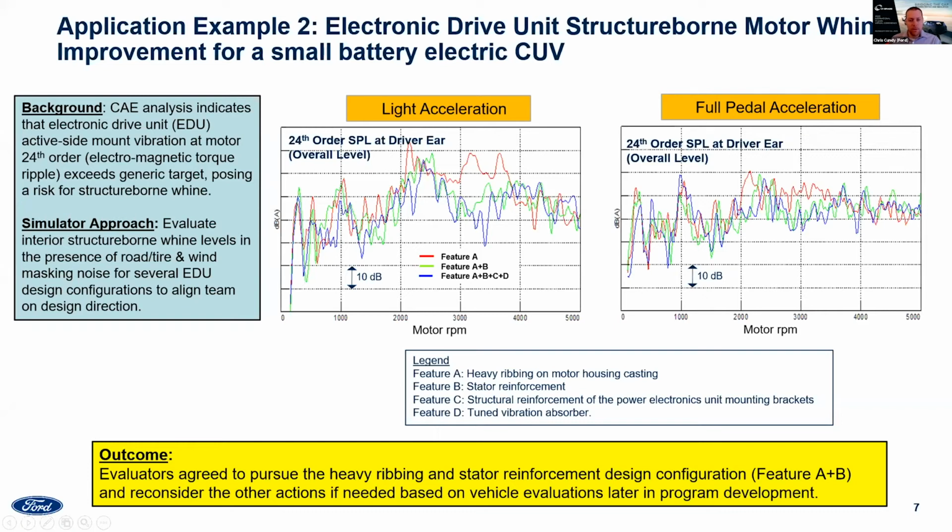could you really hear the structure-borne whine noise? So these CAE predictions of the mount vibration from the electronic drive unit were combined with estimations of the mount stiffness and a vehicle vibroacoustic transfer function to predict the whine levels. So we conducted listening evaluations of the interior whine noise with different combinations of structural features of this electronic drive unit.